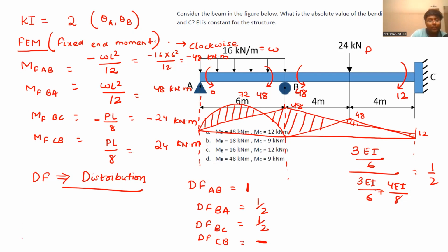I am giving you a hint on how to draw. Now, can you find every reaction from every side? If you know these reactions, can you cut the beam into sections? Take the section till a point such that there will be some loading change, or some EI change, or some material change, till this point this section will be valid.